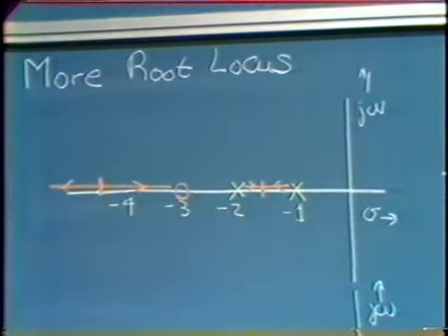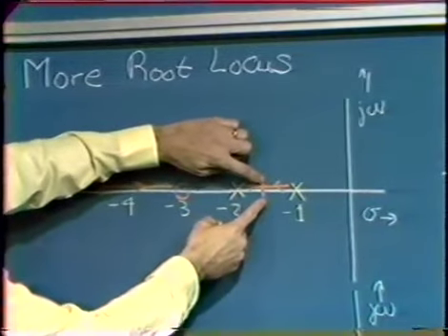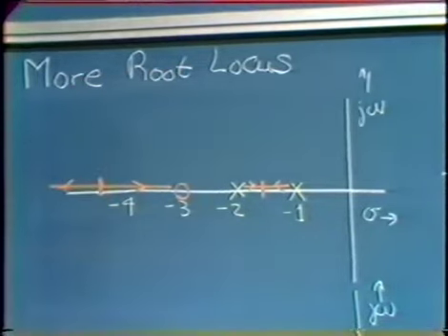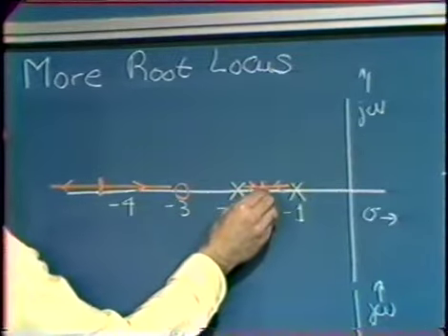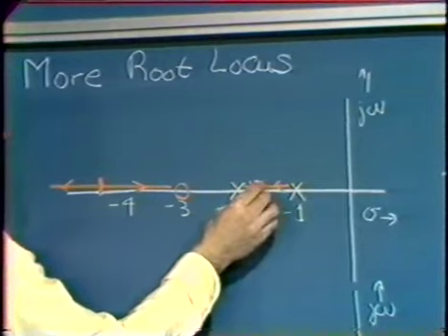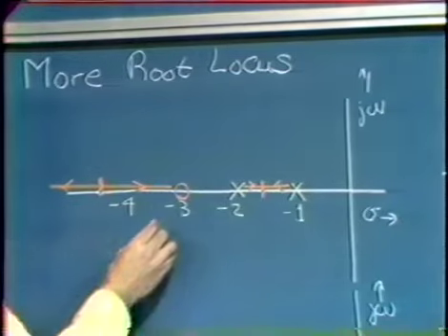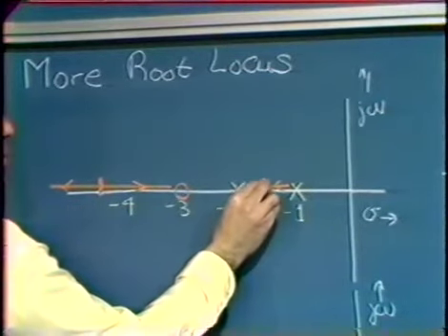The only thing that can happen is for these branches to circle around in the S-plane, eventually reaching this point. If, furthermore, we keep track of the trigonometry involved, I think there's a proof from high school geometry that basically does this, we find that what we need for a trajectory in order to keep the angle condition satisfied is, in fact, a circle that's centered on the zero.